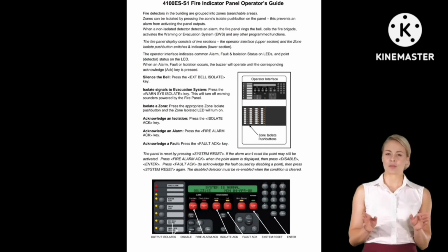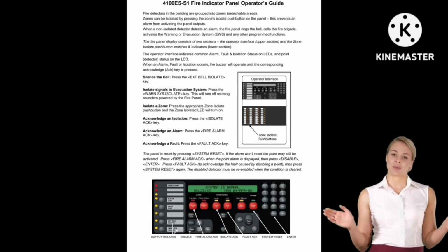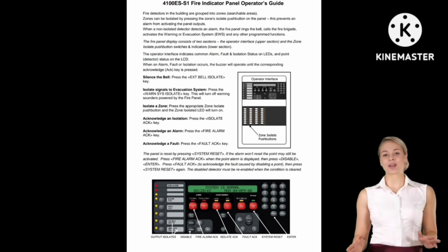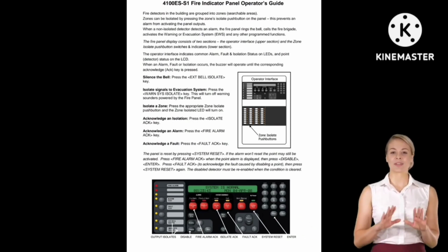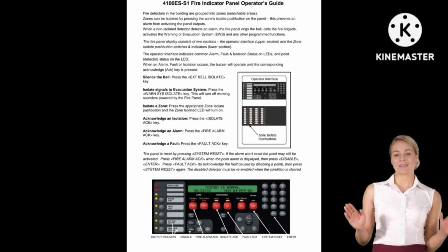To acknowledge an alarm, press the fire alarm ACK key. To acknowledge a fault, press the fault ACK key. The panel is reset by pressing system reset. If the alarm won't reset, the point may still be activated.